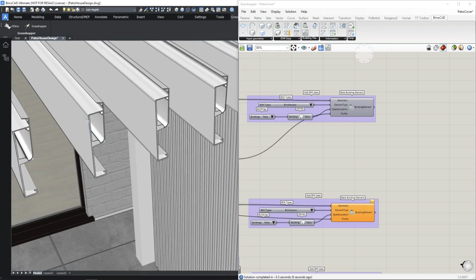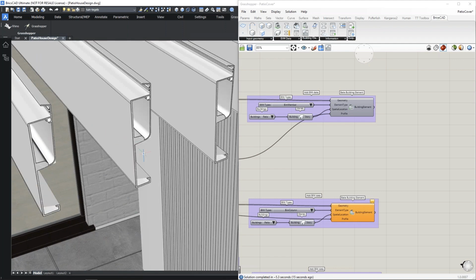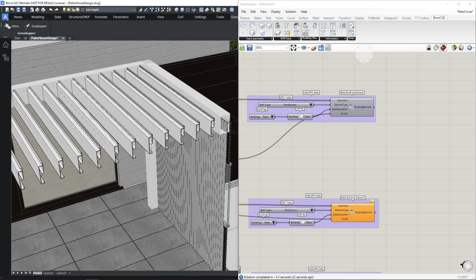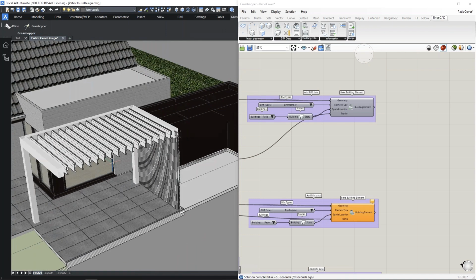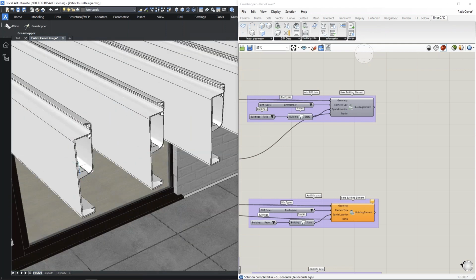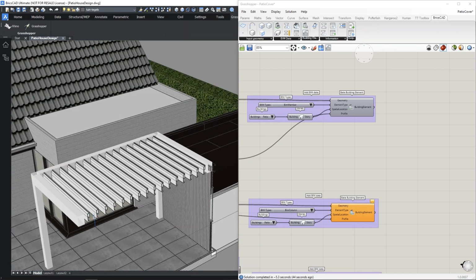you see that now I have this intricate shape, and it's really showing you the possibilities of the mix between the profile library of BricsCAD and the Grasshopper connection. So upon baking, you can even complicate your model even more without having to burden your Grasshopper script with very difficult shapes. So that's what I wanted to show here. But remember that once you bake, everything is really set into BricsCAD. From then on, you can start to model things in BricsCAD.